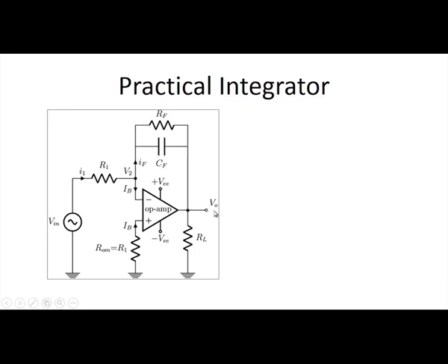If you derive an equation for the output voltage as well as the gain of the integrator, we will notice that the gain of the integrator is not going to saturate for the lower value of the frequency. So, we will see the derivation now. Here, consider ZF as the parallel combination of RF and CF.